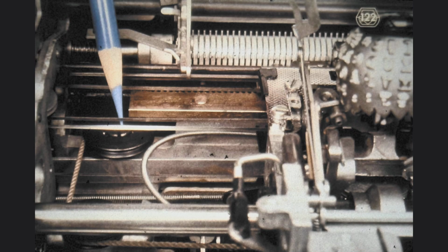Up until this point, the rotate tape was installed with absolutely no twist in it. When we go from the left rotate pulley, the pulley situated on top of the rotate arm, into the carrier, we have to introduce a half-turn twist for the first time.